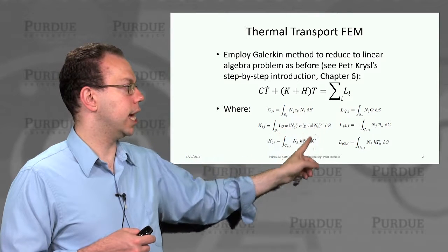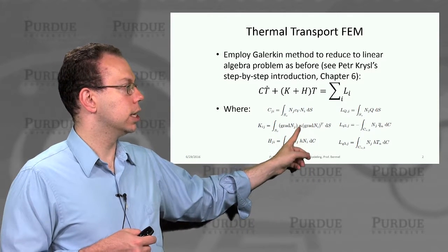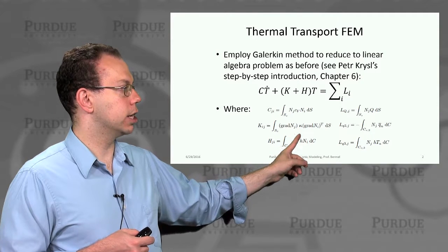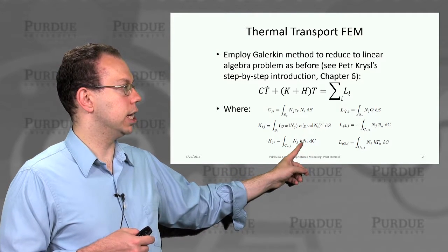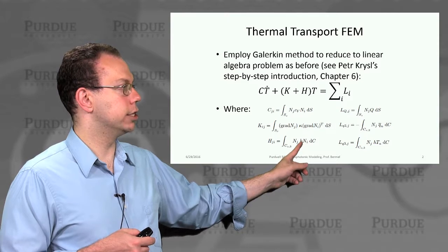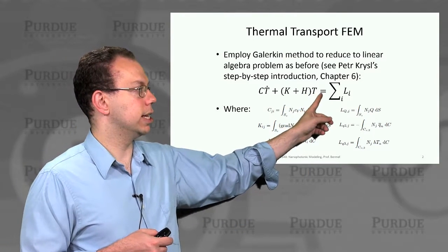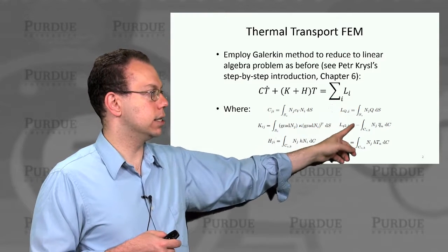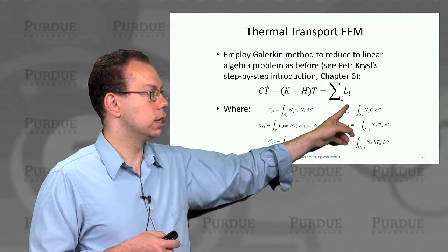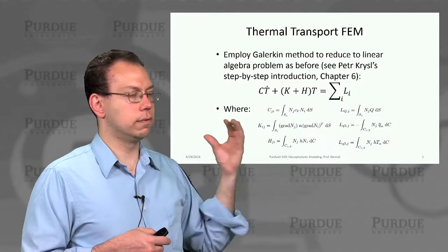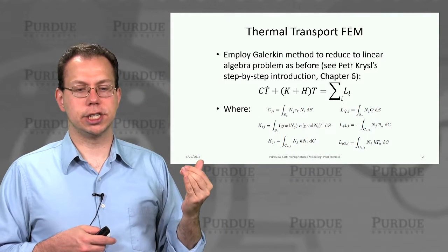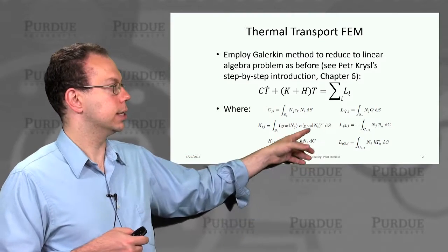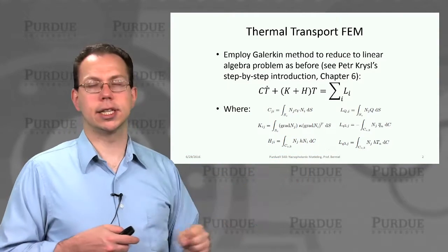And then you have these K and H components. K we'd already talked about, and this was directly derived from conduction. And then there could also be a convective term, H. So this is basically being added to this K for conduction. And then this Li is a bunch of boundary conditions for the volumetric generation or dissipation of heat plus the convection on that surface.